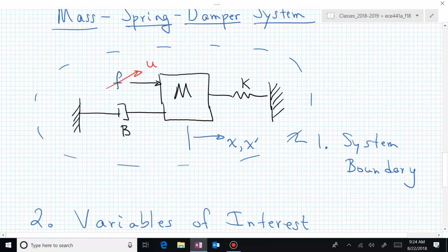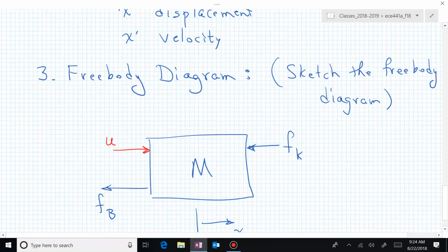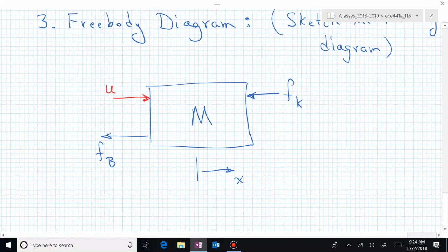The mass of that object gives me an inertial force that opposes the movement to the right. So I actually have one more force in this free body diagram that I like to put in as a dashed, but this is now the inertial force, F sub I. And that's now all of the forces for this particular mass.